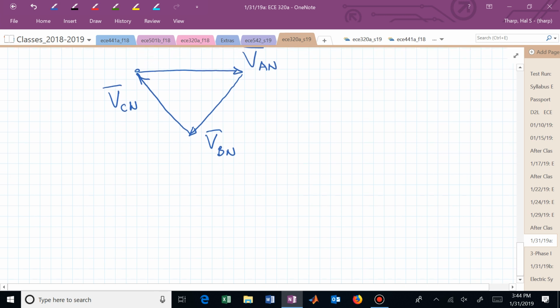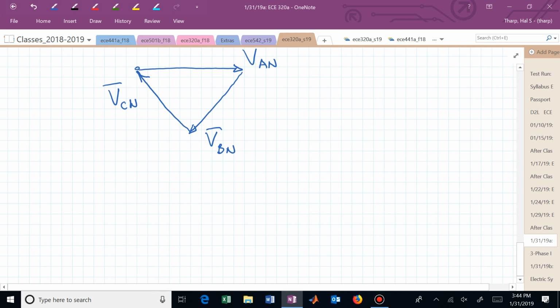But where were we? Plugging something into the wall. It now is 0 to 170, minus 170. And then it does that 60 times a second. But you now know how to compute the RMS of that. You now divide that maximum by the square root of 2.